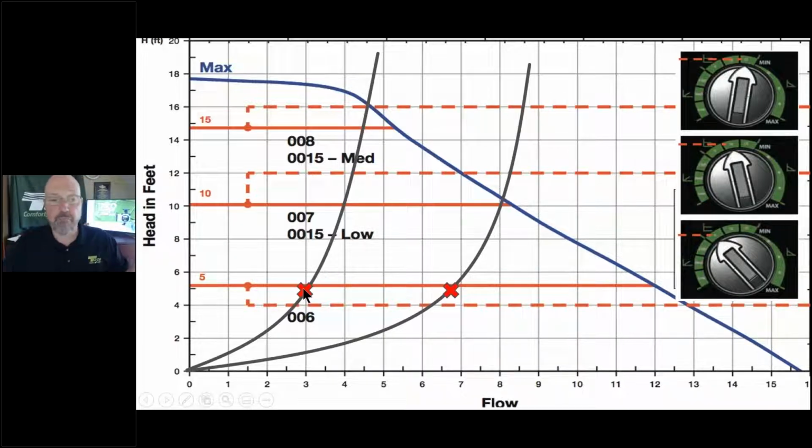So in zone valve mode, it's going to bop back and forth on the horizontal, and disregard this part of the circulator. You put it on 10 foot head and we're operating up here. Yes, we're going to overpump based upon our designs today, but we're still full speed, 44 watts, all my zones running. I'll run out here and then it'll drop back to here as my zone valves open and close. So I hope that makes sense.